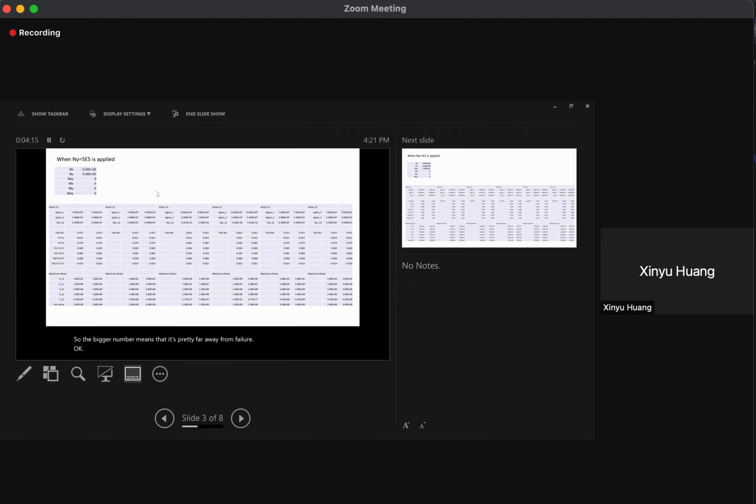All right. Now, I did a little bit of a numerical experiment. Instead of applying stress in x direction, I apply stress in y direction. That's a little bit higher stress here. So everything now changed. I bring several layers much closer to failure now. It was 0.186, now it's 0.471. It's just halfway to the failure point. This layer, and this one is 0.621. That's even closer. All right, so overall, this is much closer to failure.